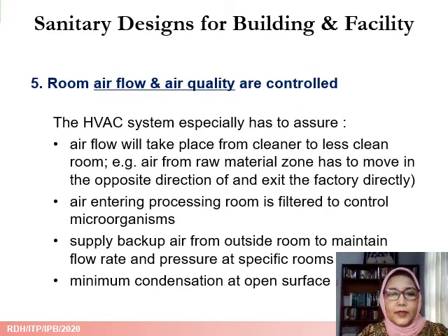The fifth principle requires that room airflow and air quality are controlled. The HVAC system especially has to assure that airflow only takes place from cleaner to less clean rooms. Air entering processing room has to be filtered, and the supply of backup air from outside room to maintain flow rate and pressure at specific room must be available, and minimum condensation at open surface.